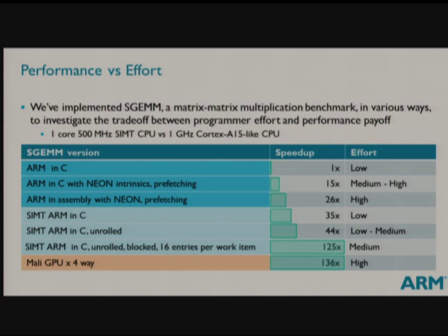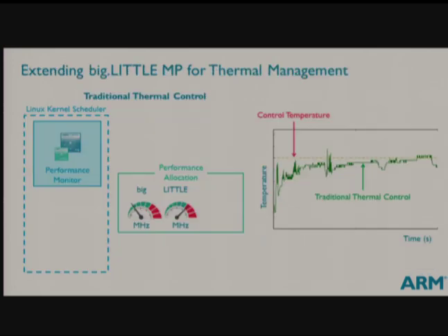But if you go back to some of those drivers and the real performance needs we'll need to make those lane recognition and hazard detection systems work, it'll be worth putting investment into some specific codes in order to be able to extract significant performance. So I do think when you look at system architecture, you'll find different ways in which you use transistors to solve that problem. Now, obviously, you've got to manage the power in these systems. There's a whole lot of work to be done in how you do the control automatically of does the workload run on the big core, does it run on the little core, what voltage, what frequency, when do I switch it,